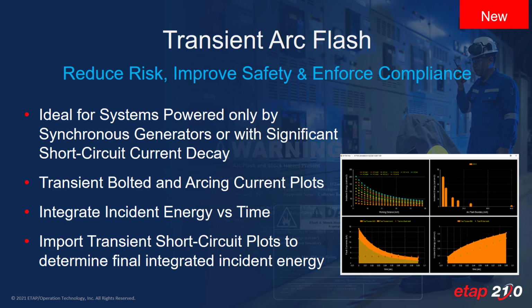Up to today, all arc flash standards provide examples of incident energy calculations only using constant symmetrical RMS voltage short circuit currents. Of course, IEEE 1584-2018 makes mention that systems with decaying short circuit current are likely and should be considered, but provides no clear methods to evaluate the incident energy as a function of time for such systems.